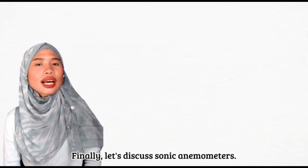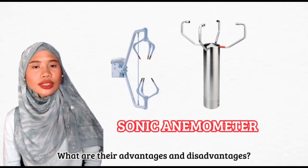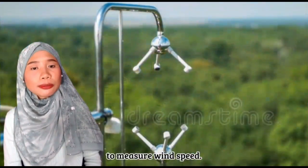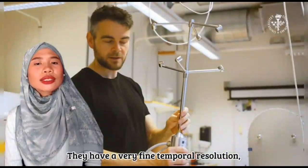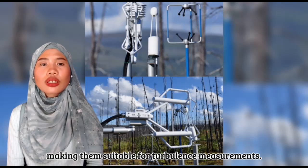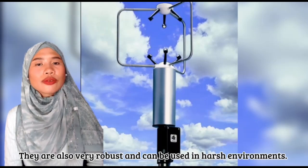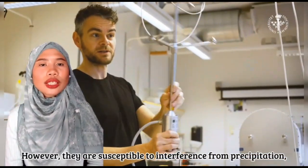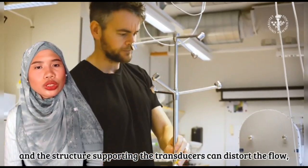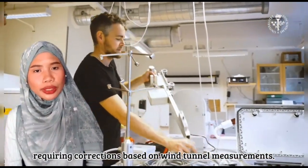Finally, let's discuss sonic anemometers and what are their advantages and disadvantages. Sonic anemometers use ultrasonic sound waves to measure wind speed. They have a very fine temporal resolution, making them suitable for turbulence measurements. They are also very robust and can be used in harsh environments. However, they are susceptible to interference from precipitation, and the structure supporting the transducers can distort the flow, requiring corrections based on wind tunnel measurements.